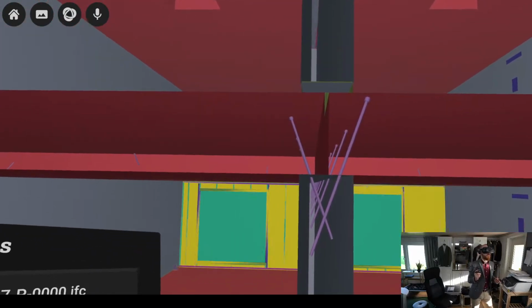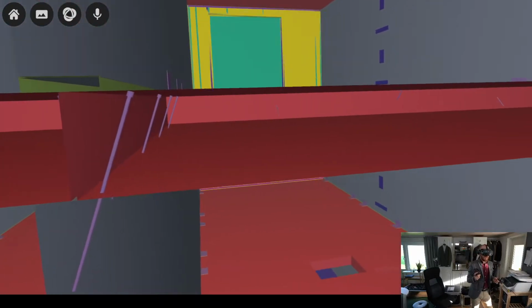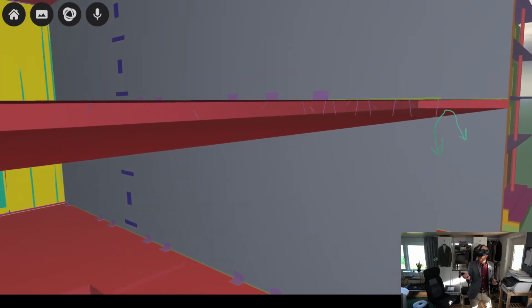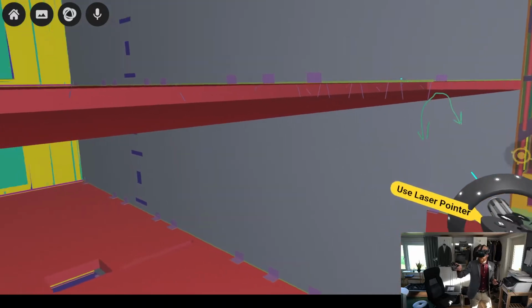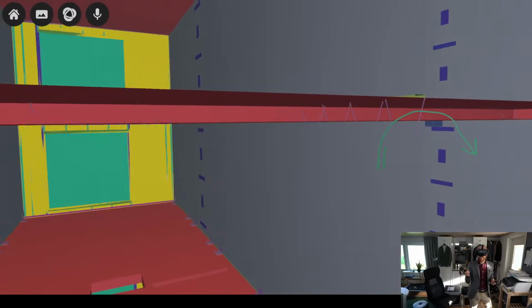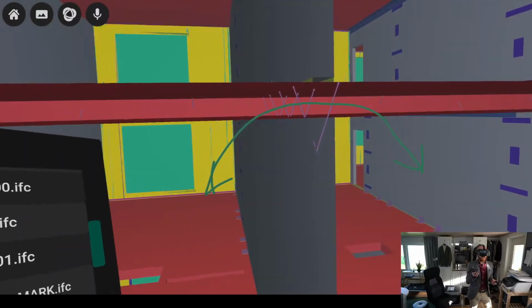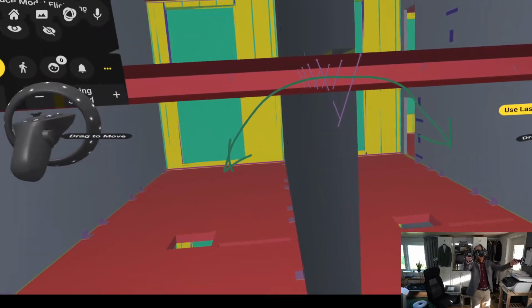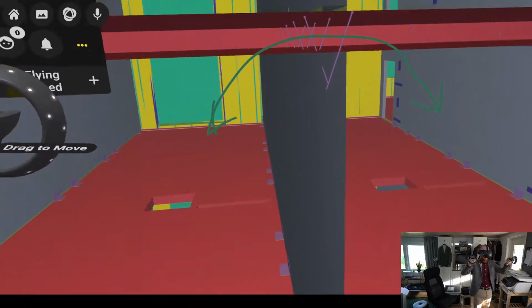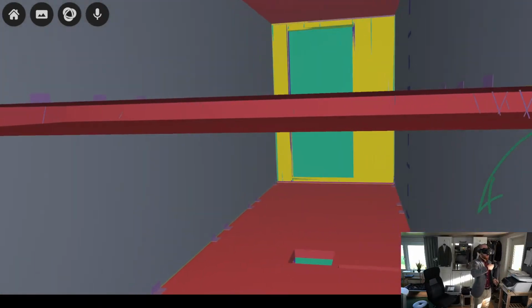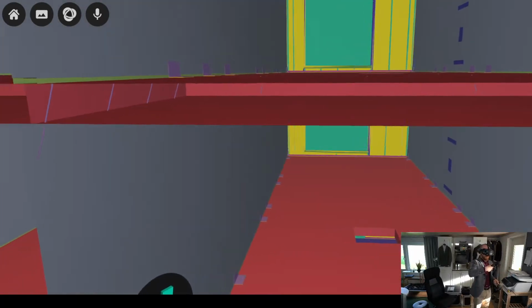Another benefit is that when you have the continuous slabs like this, you get a stiffer boundary condition here in the junction, which means that you will have less flexibility in this one. They become stiffer, and that can be positive with regards to low frequency sound insulation.